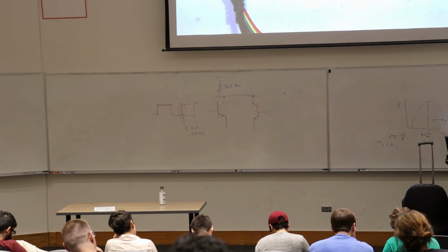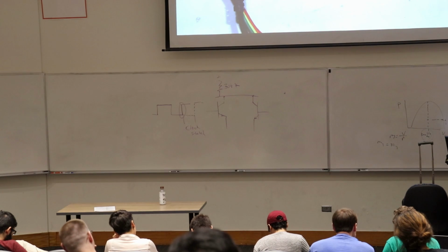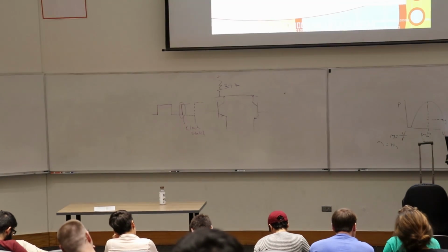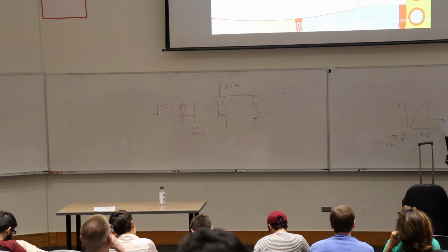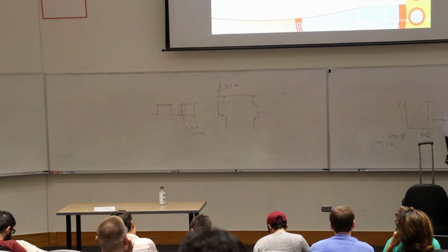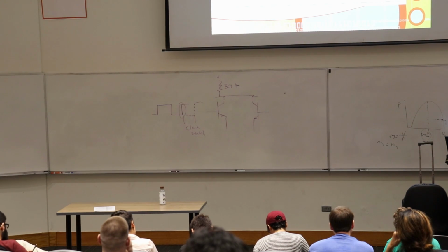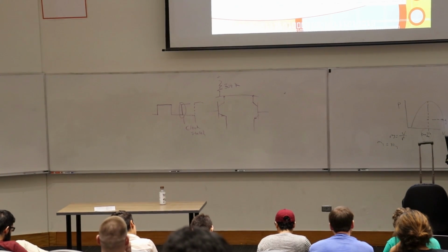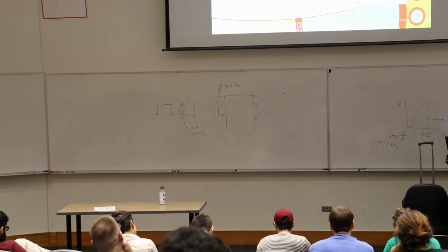Okay, so here's the I2C block diagram. So here's the block diagram, and you see the 2 pins, and here is the open collector driving those pins. And then of course you have this gate reading the data line, so that it can store the data, check for bus collisions and things like that.